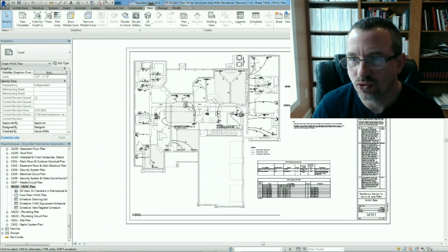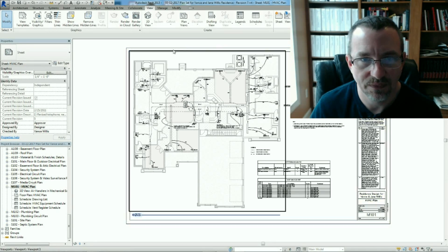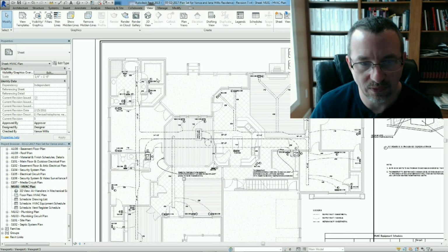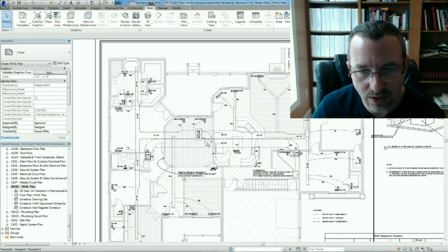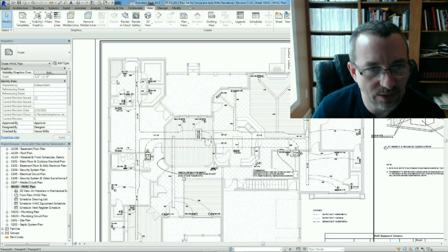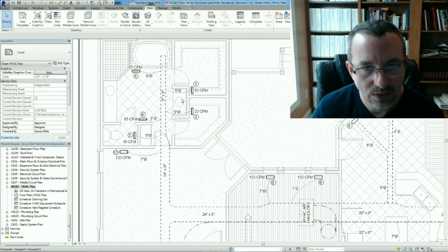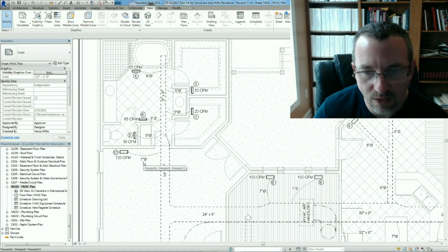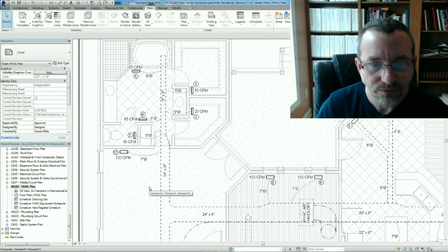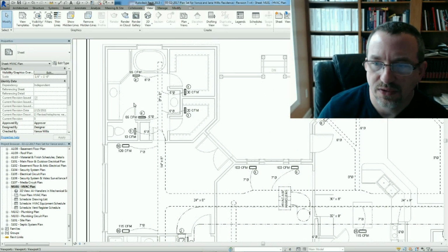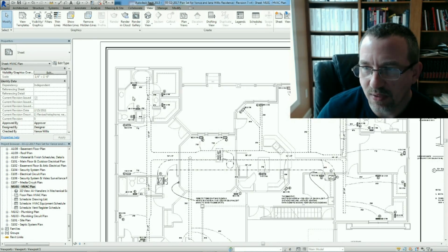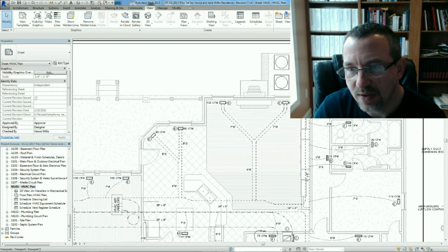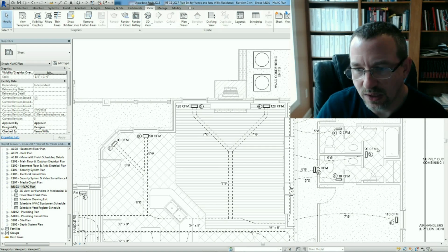Okay, here's the actual drawing page view that is the HVAC plan, and we'll zoom it up a little bit where you can see what's going on. You can see the air handlers are here. This is where the return air system is. You can see that trunk. And everywhere there's one of these, you can see all these floor registers shown, and each of these little dotted lines is a detail line I drew in there with the diameter called out for the flex vent. So the trunk's here, and then you can see all the takeoffs. There's quite a few. It's a pretty complicated system. I probably went overboard on it, but hey, it was my dream house, so I thought I'd do it up nice.